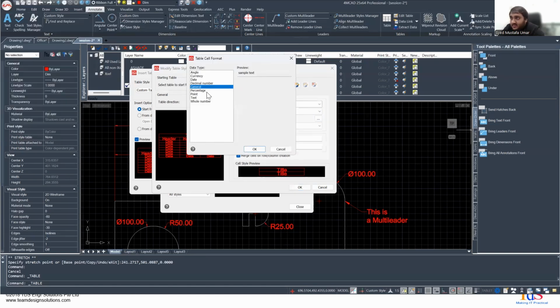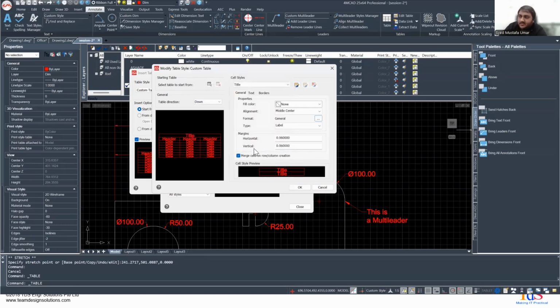It's going to be a lot over here. You can change a decent amount of things. So what I would suggest to do is always go through all three of them, go through each part and then adjust the color, adjust the properties over here, ideally to ByLayer, so that all of your table resides within the same layer.